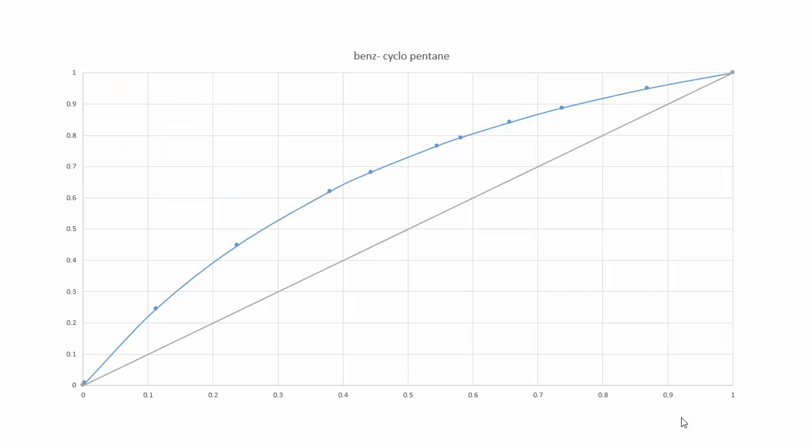So you have seen this equilibrium line. The top operating line will be this line. The top and bottom operating lines coincide on the diagonal. XD here we have 0.93. Here is the point, and we have XW here. So this will be your operating line. You have to make sure that at total reflux, the slope will be 1.